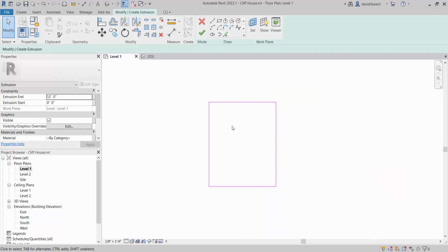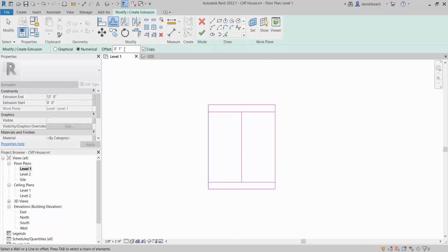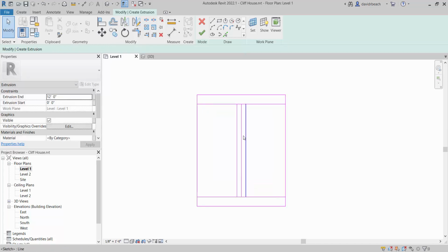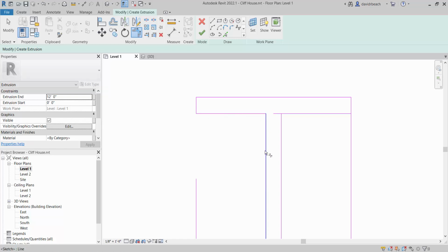Right? So those were the outer perimeters of the column. The next thing that I did with that was inset everything 1 inch to set up the thickness of the I-beam, drawing a center line, offsetting that center line 0.5 inches this way and that way, and then a lot of splitting, 1, 2, 3, 4, and a lot of trimming.